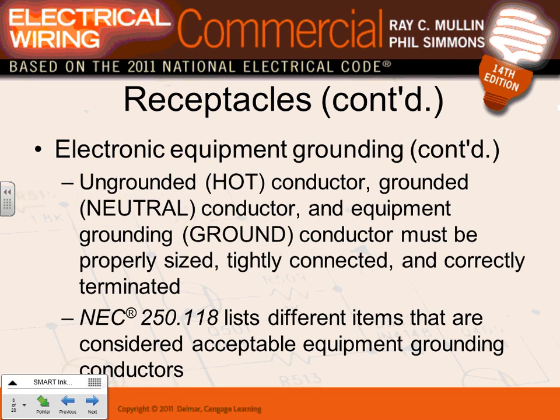The only thing I want you guys to understand is that grounding sensitive electronic equipment is a big deal. The only thing you need to do, Zach, is pull an isolated grounding conductor number 14 all the way to the service. Number 1, that, and number 2, surge protective devices. Those are the 2 things that you can do. Okay.